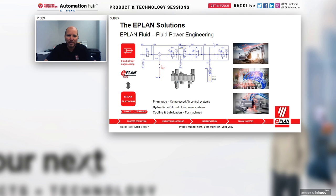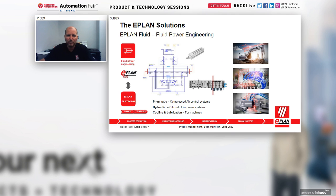Then we have EPLAN Fluid. EPLAN Fluid is our solution to design fluid power applications. So whether you work in hydraulics, pneumatics, or cooling and lubrication systems, you can use the ISO 1219 standard symbol libraries to put together your control systems for your compressed air. So here we have an air preparation unit. Here we have a valve manifold control, and we work together with Encompass partners like Festo as well, that can easily download the components from the Festo configurators or even from the data portal. You can easily place those components in here in your design environment, and you can use that information to also drive the design.